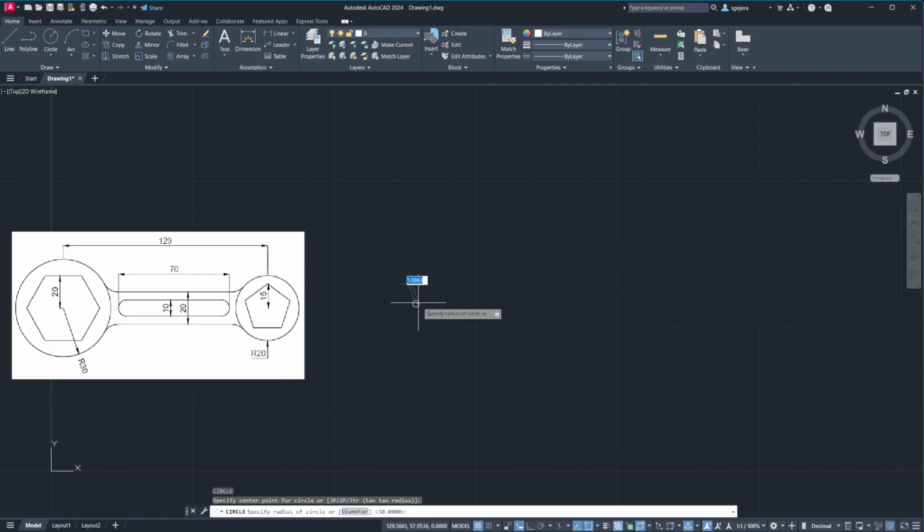So if I draw a circle, by default, ang input dito, so we call this as dynamic input, no? Kasi kunwari if you increase the size of the circle, makikita nyo na nagbabago yung numbers sa loob, yung naka-highlighted in blue na numbers. Pero you can actually input a specific number, no? And this is how we usually want to do AutoCAD, no? Ayaw natin na mag-estimate tayo, i-increase lang natin hanggang mag-30 siya, like so.